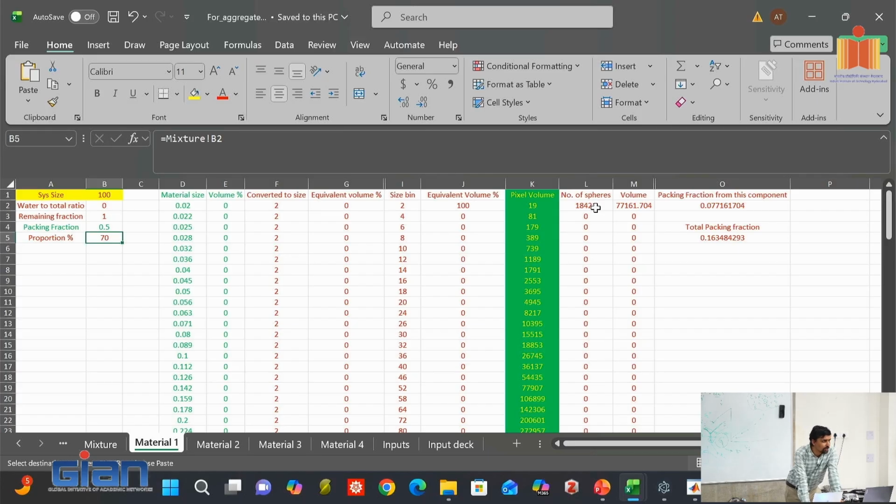Remember, it's not making the 2 micron particles sit side by side so that it fills up everything. It's not 50 elements in a row, 50 elements in a column. It randomly starts at a point and distributes at random points to create a microstructure. So it won't reach the maximum limit of 2 micron particle. But with the random seeding, you can start playing around, asking what is the packing limit I can go to? I think this one started with 55 and still could not do 55.